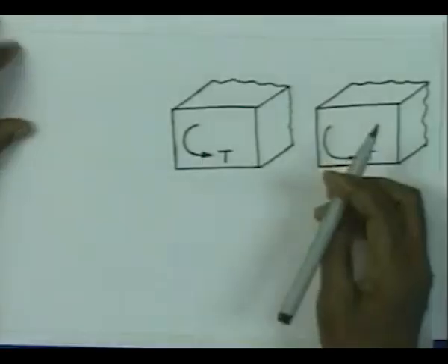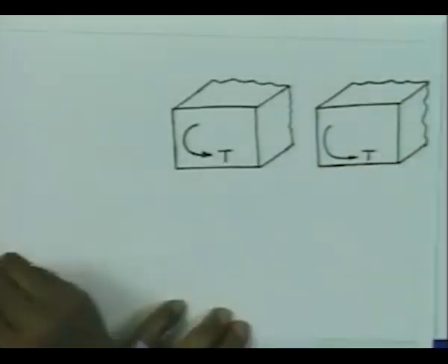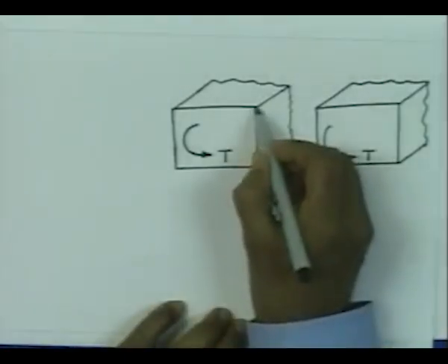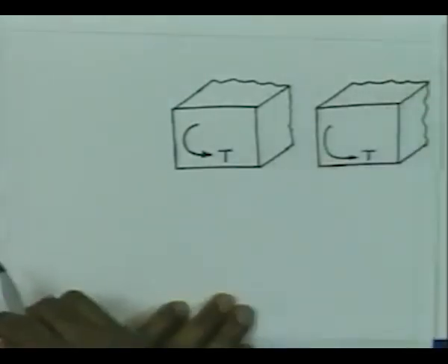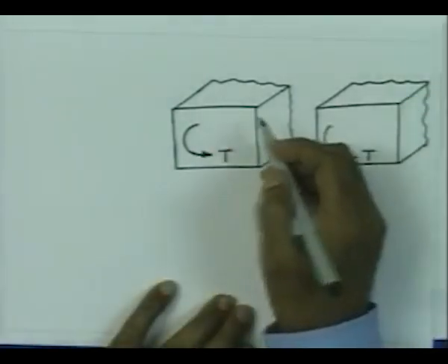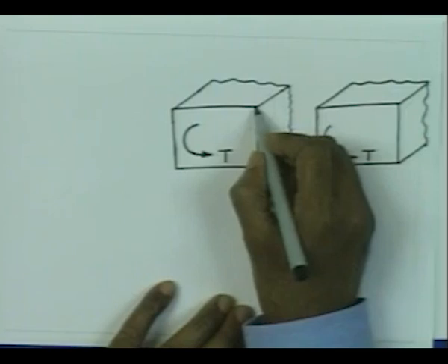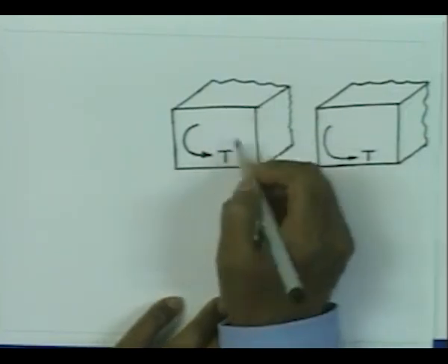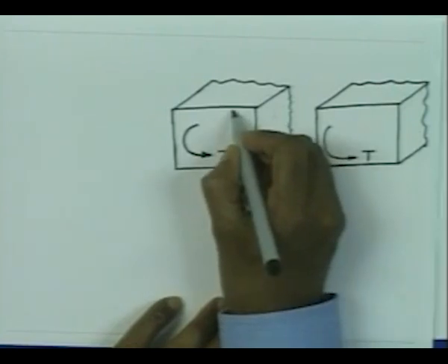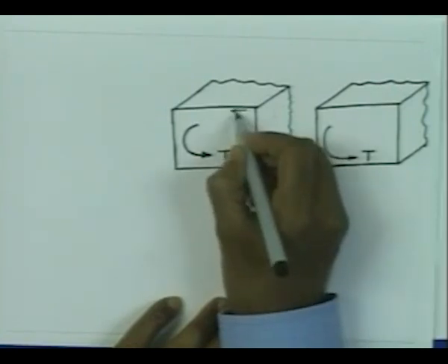The answer to this problem can be obtained in 3 different ways. First of all, let us consider this rectangular section and concentrate at this corner. So, torque is acting like this. This is the axis of the shaft. If you consider this point, the stress is going to act parallel to this boundary in the same sense as the torque. So, we will have stress acting like this